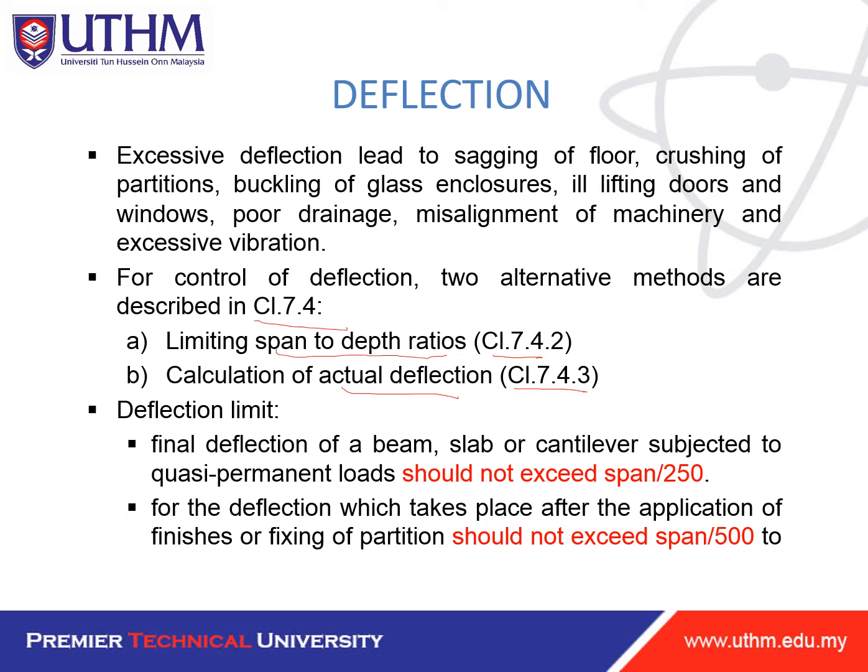For deflection limits, the final deflection of a beam, slab or cantilever subjected to quasi-permanent load should not exceed span over 250. The deflection which takes place after the application of finishes or fixing of partitions should not exceed span over 500.